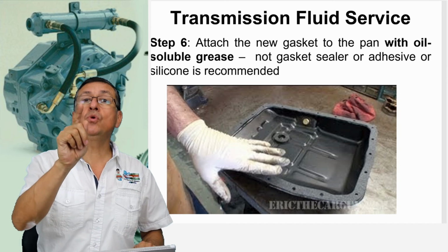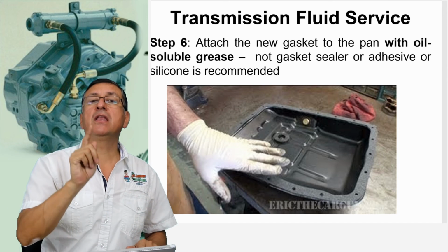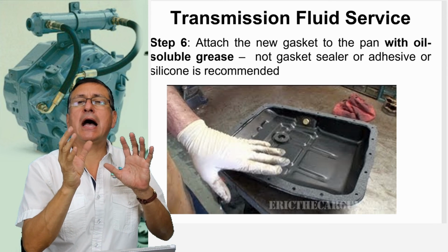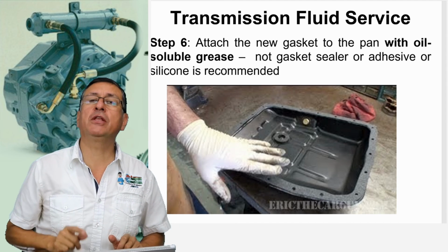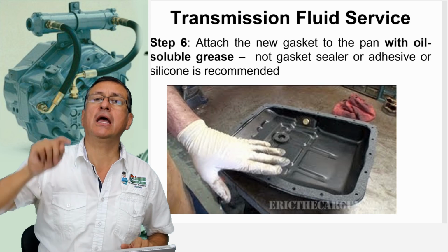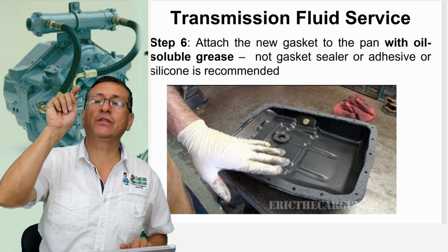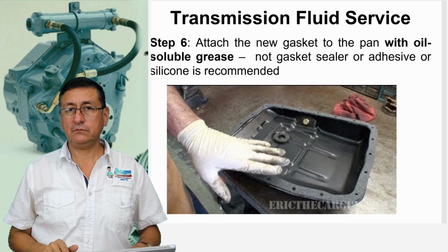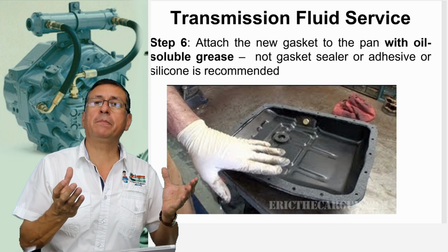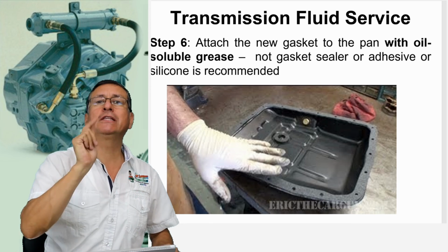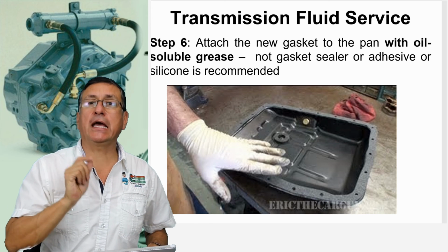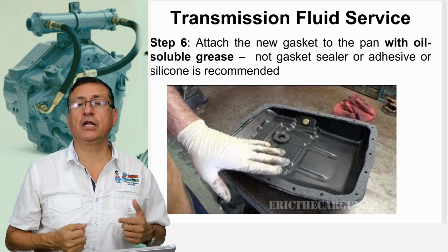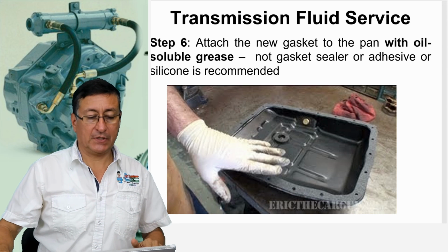Alright, if you lose one of those bolts, never try to put in a bolt with a different thread, because you damage the aluminum thread on the housing of the transmission, and 100% sure that you have a leak in the future. Before you put back the oil pan, check all the bolts, all the threads. And on each bolt, I recommend using Loctite, in order to avoid leaks.